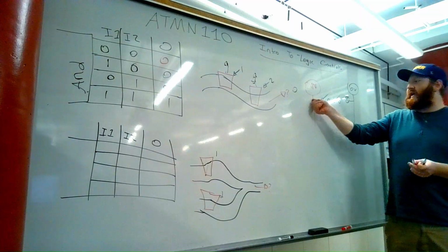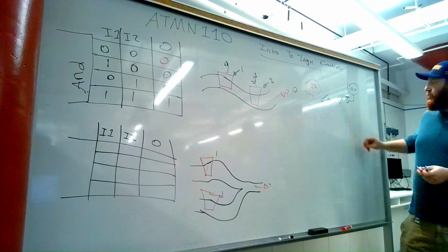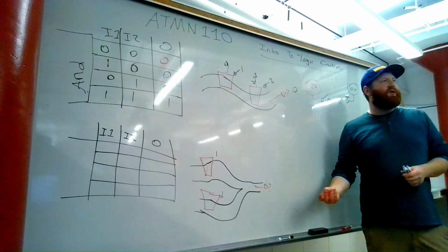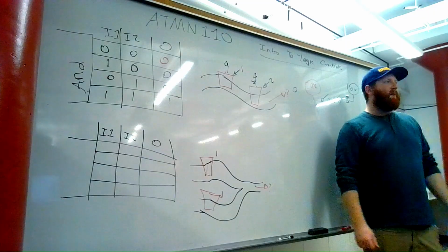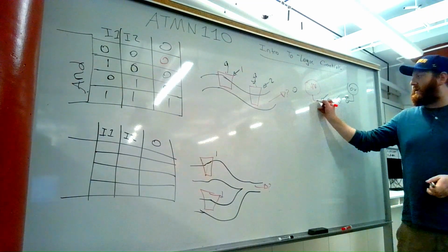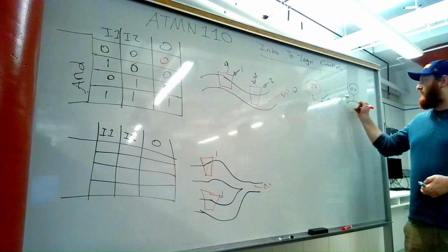We don't really need these hanging wires. These hanging wires are great for when you're designing circuits and drawing them by paper. As soon as you move to Automation Studio, don't use them. It's not part of a professional circuit. You just have the actual circuit outline, right? So from here to here, here to here, here to here, and back to 0.